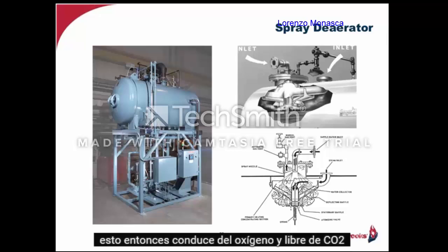This then drives off the oxygen and free CO2 through the automatic gas vent before the deaerated water passes through the spring-loaded atomizing nozzle into the feed tank.